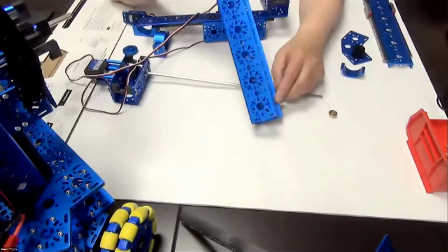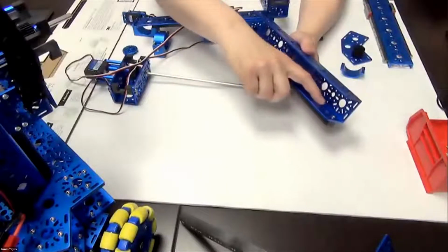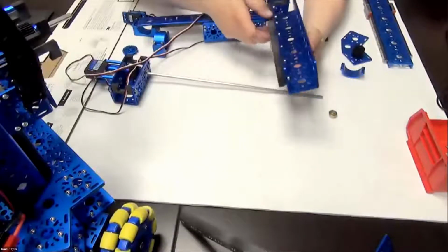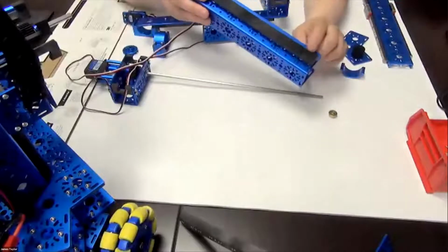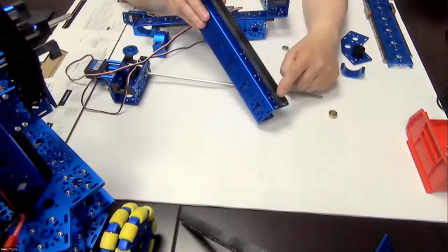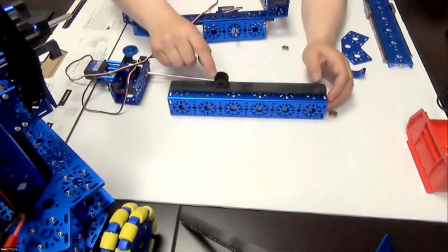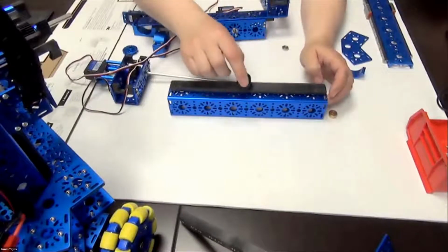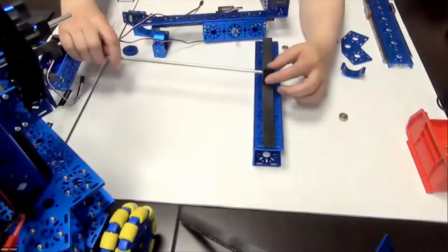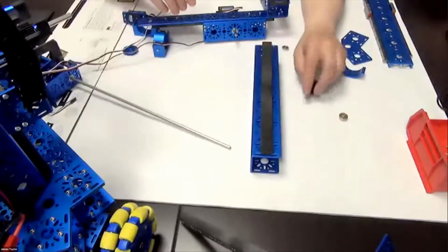If you take a look along the back side here, inside of the rack, there'll be brass inserts inside your rack. So this black piece will allow you to center that and fasten it, and you use M10 socket head cap screws to mount the rack onto the channel, right? Once you've got the rack mounted onto the channel, the basics is that this pinion gear is what's going to translate that rotational motion, okay? So as a shaft, okay, turns along here, it translates the rotational motion on the rack and pinion.